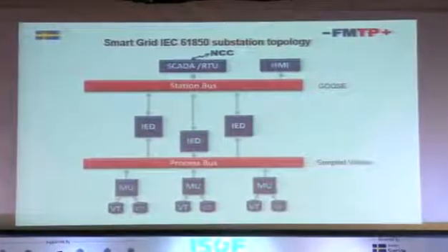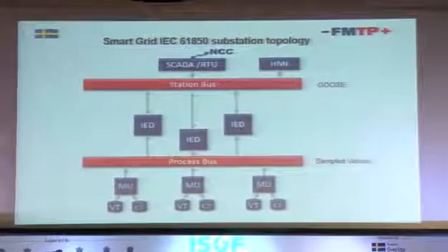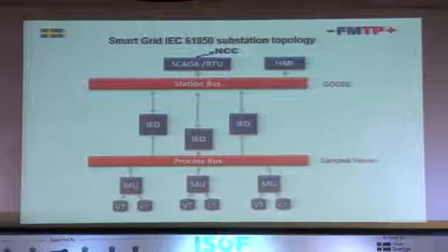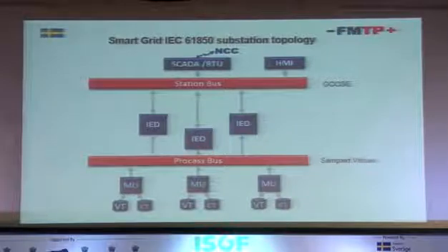Now, just a very short picture showing the topology, a schematic of a substation and the two protocols that are inside the station. There is a well-known SCADA communication, which is mainly used from the station outside to the other stations or to the control center. There is also SCADA that commands the so-called HMI, all the visualization. But when it comes to the process inside, we have the protocol called GOOSE that interconnects digitally the different elements in the station.